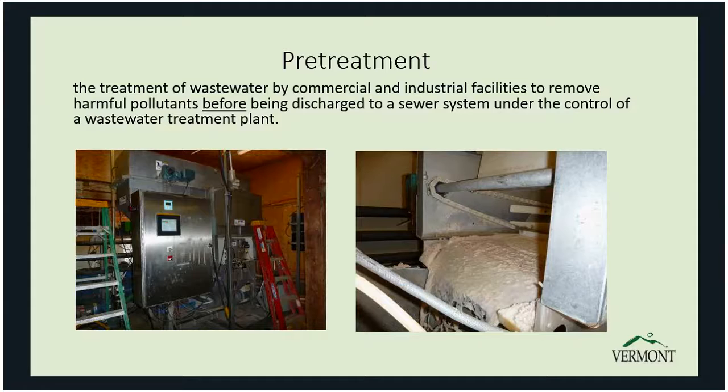This is a picture of a dissolved air flotation unit. You can see on the right those solids, which contribute to the high-strength waste, being skimmed off the top and separated before the liquid gets discharged. This is something you'll commonly find in large breweries and dairy manufacturers.